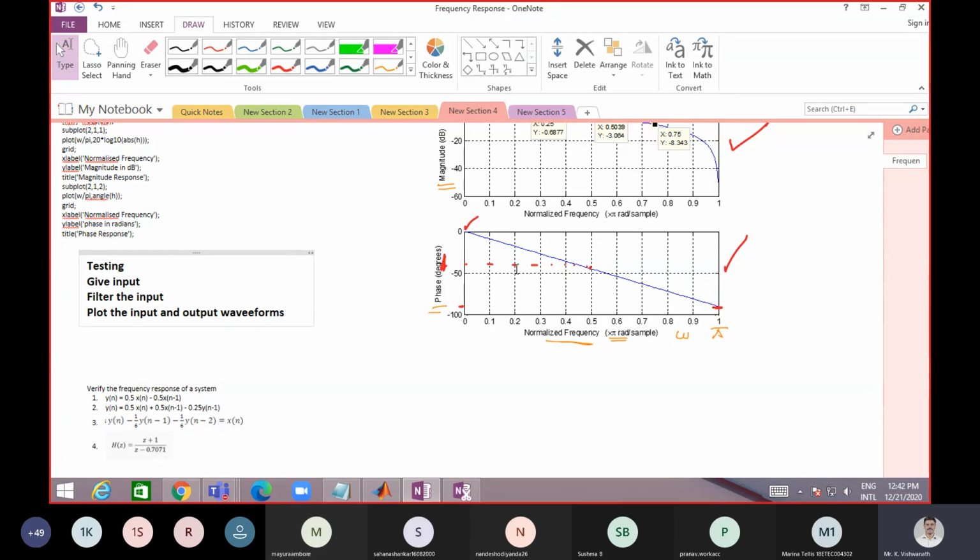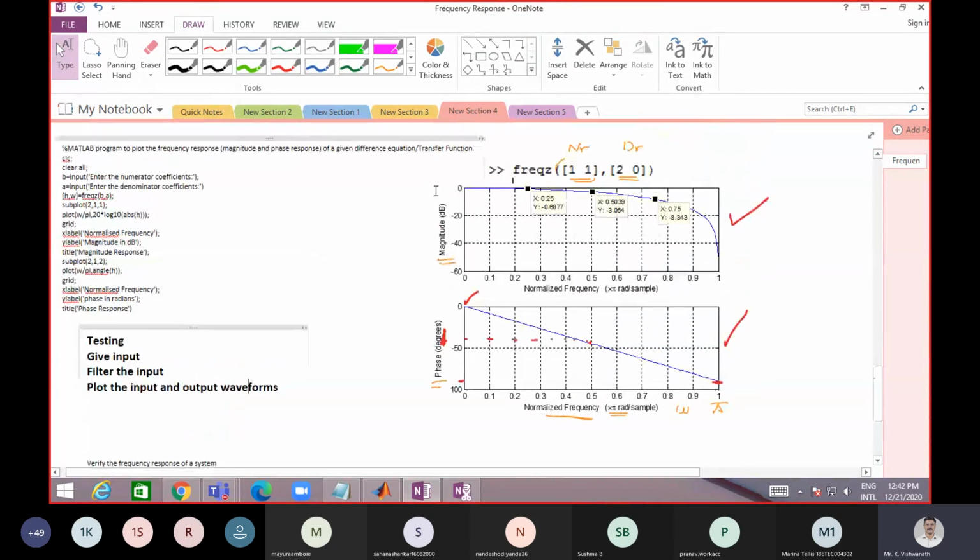This is the template that we are going to try. So what we'll do is, see, as per this, what it says, if you give a DC signal, DC will not be attenuated. It will be with 0 dB. That is, it's not attenuated. Whereas when you give high frequency, like very pi frequency, then that component will be attenuated.